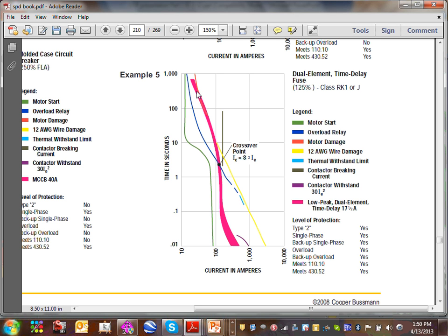Well, their tolerance is less than the circuit breakers, because circuit breakers are mechanical action, it needs to heat up. So when they give you that thick curve, we really don't know exactly when it's going to open, but we guarantee you that it's going to open between this value and this value. Plus or minus 10, 20%, above and below, that's when the fuse is going to burn.